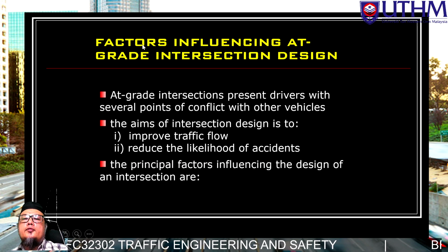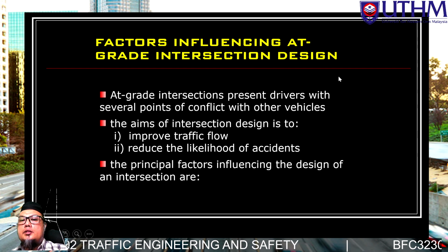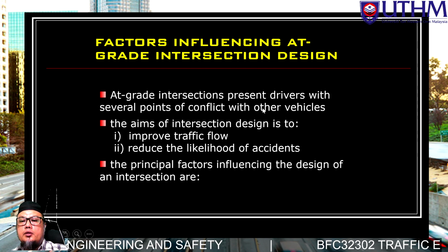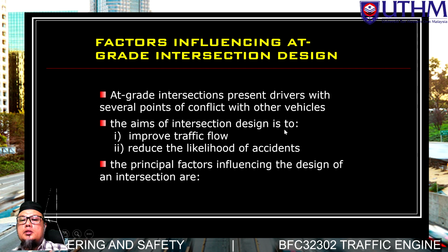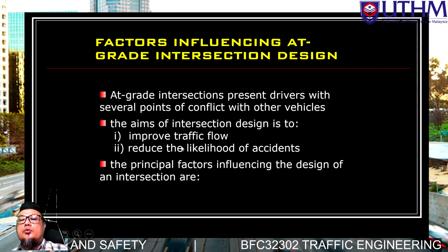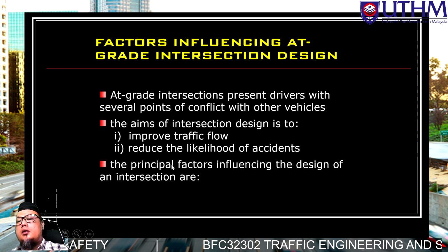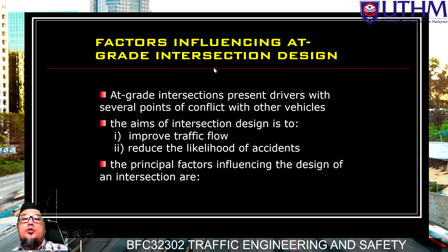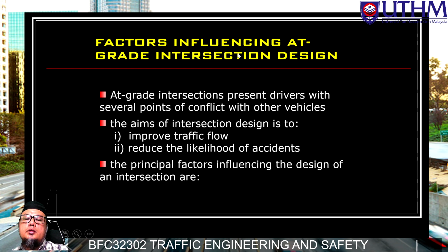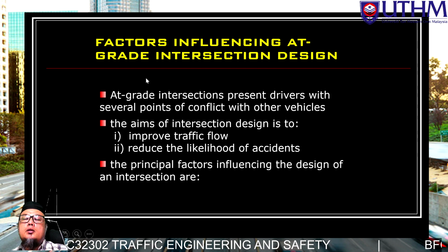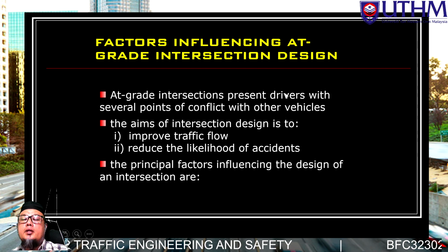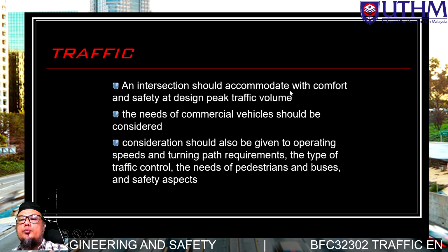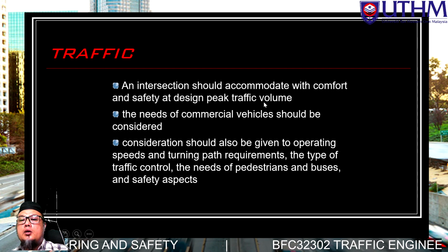Okay, next, factors influencing at grade intersection design. At grade intersection design presents the driver with several points of conflict with other vehicles. The aim of intersection design is to improve traffic flow and reduce the likelihood of accidents. Okay, the principal factors influencing design of intersection. This one is under at grade intersection, not under separation, because these are the factors for at grade intersection only. And the intersection should accommodate comfort, safety, and be designed for peak hour volume.